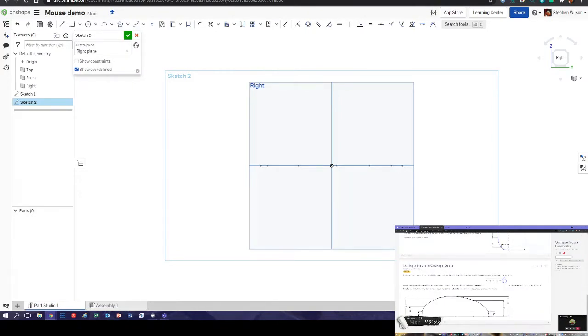Again, use the spline command and have 5 points between the start and the finish. Use the vertical constraint button, that's that there. Note the first point and end are in line with each other. The handles, 10 millimeters, I think, should be constrained vertically. Let's see what happens. So we're going from there, 1, 2, 3, 4, 5, and then down to there.